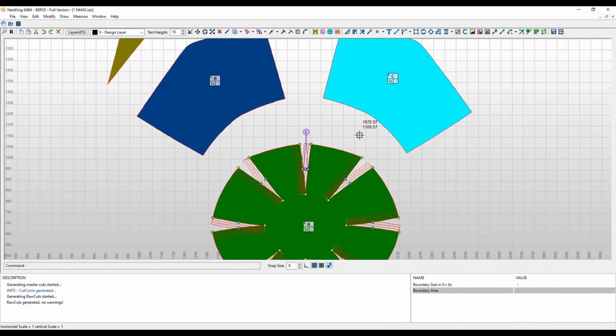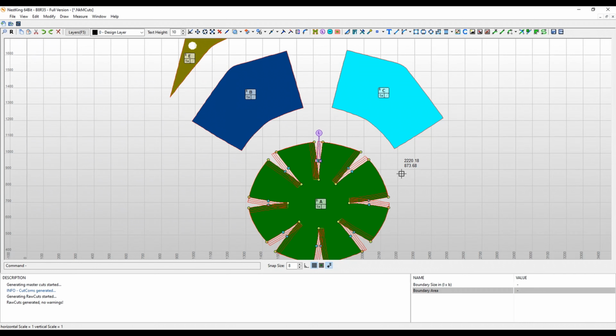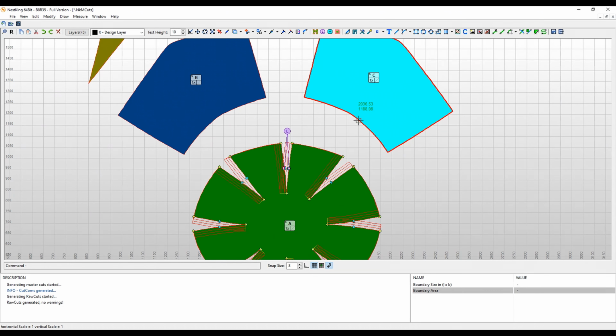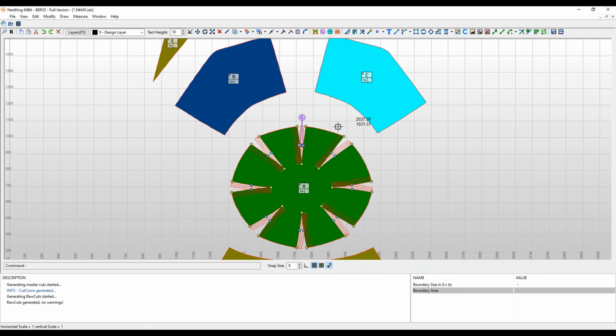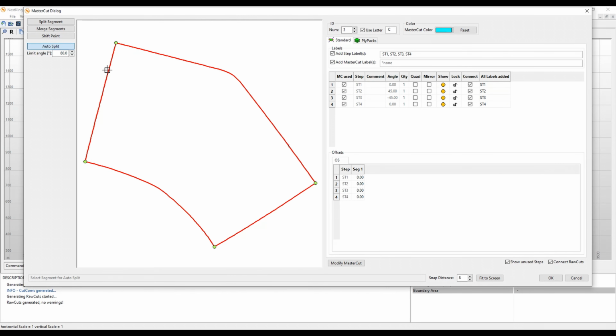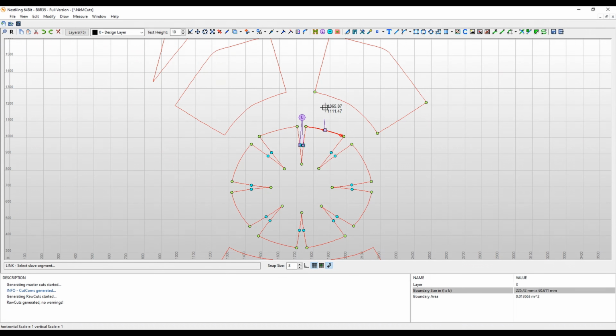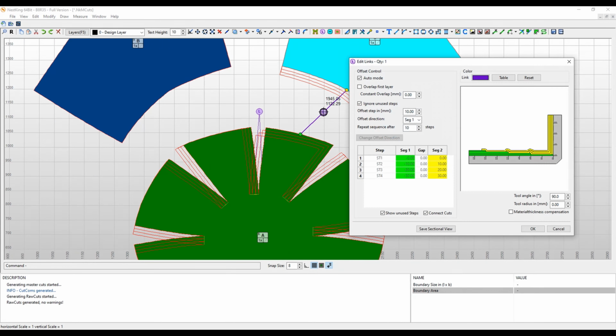Now, the next thing that you want to do, you want to continue connecting to your next ply. So let's do the connection to the blue one here. We know that the blue one, this edge is actually attaching to, like, not a half cone, but a quarter of the full circle here. So it is attaching to this line and this line. Therefore, double click here. I will auto split. Perfect. Nice. And I will create a linker from here to there. Now enter the link and check.